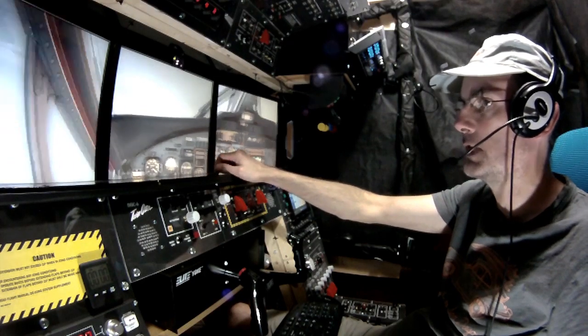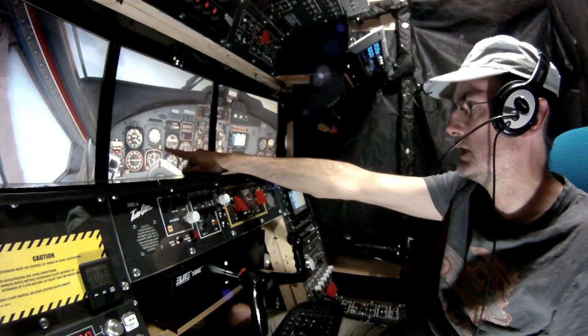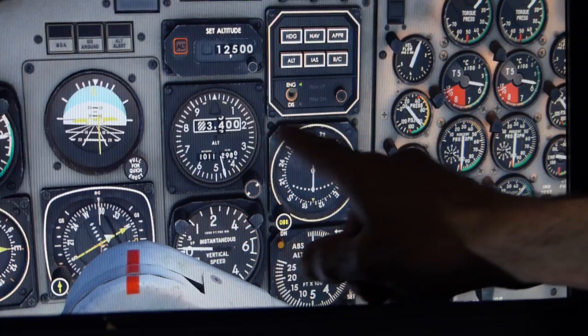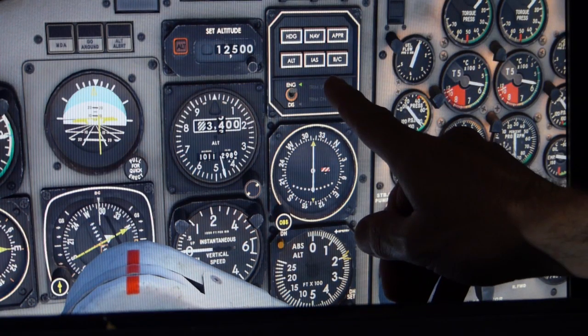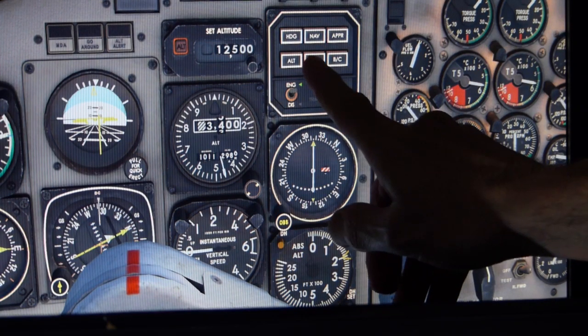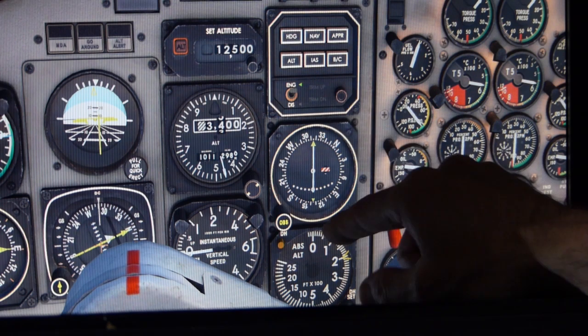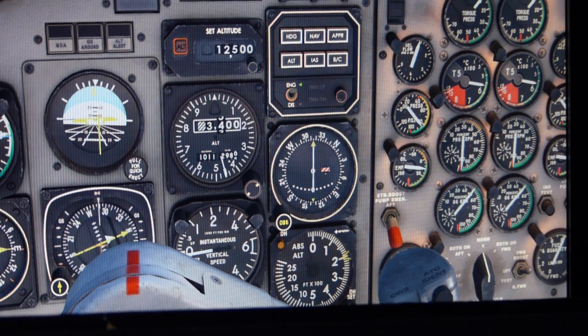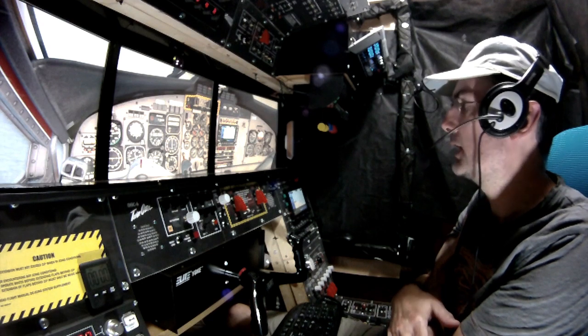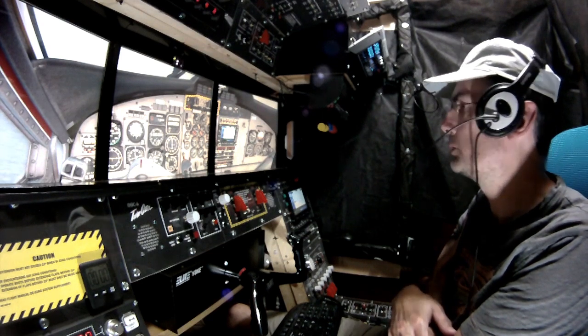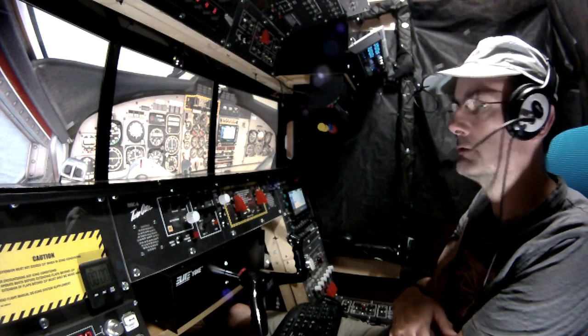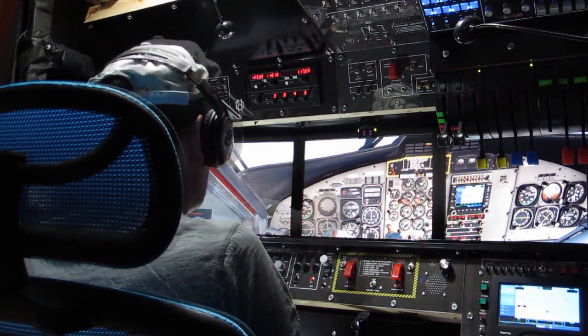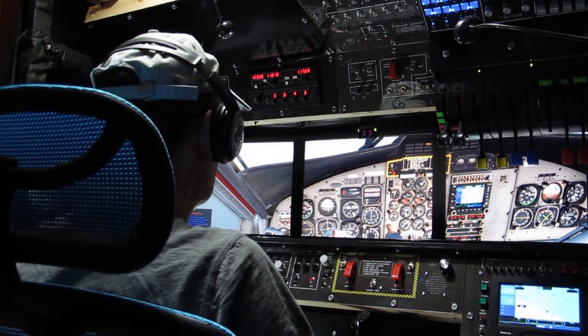Obviously what that did on the flight director was it actually set up an 8-degree nose up attitude. You remember we were on IAS hold and heading hold. It disconnected both of those modes, and so basically flew us out. All I had to do was put the throttles open and it flew us out of trouble. So that's the function of the go around button on the altitude alert.